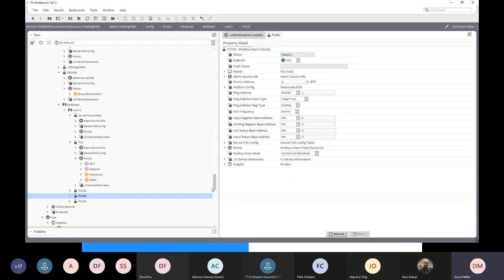And so that means that if a device is offline, the master will poll it, send a request, get no reply. You'll have to wait, time out, try again, wait, time out, try again, wait, time out, and then flag that device as offline.